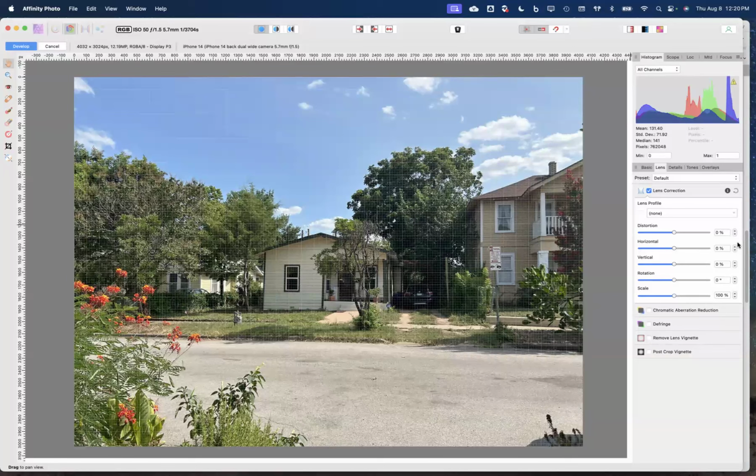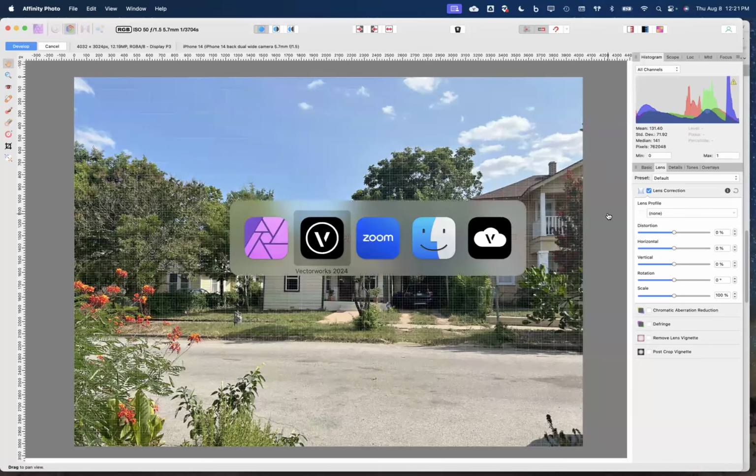So we're going to say that I went and corrected these images prior to using them for camera match. But again, it turns out with the iPhone 14, that's not actually necessary. But I would just go ahead, and any image that you use, go ahead and check it for distortion, even if you think that it's safe, just to make sure. So we'll assume that these are corrected images.